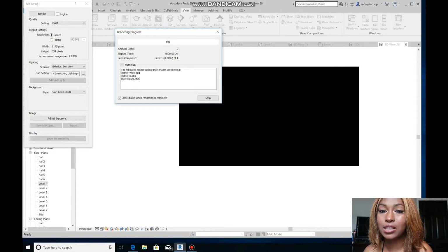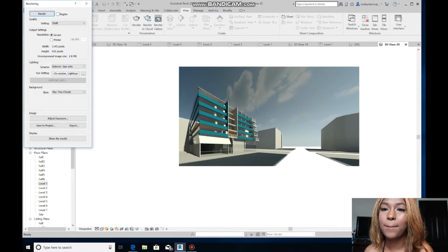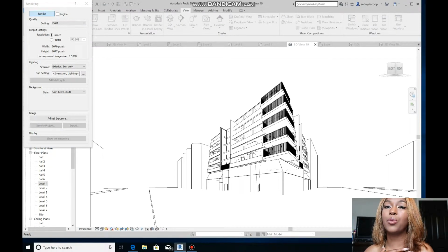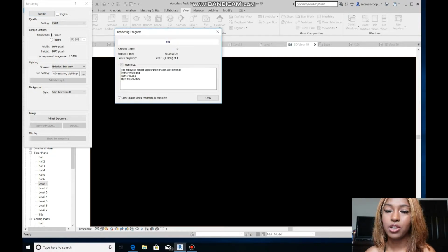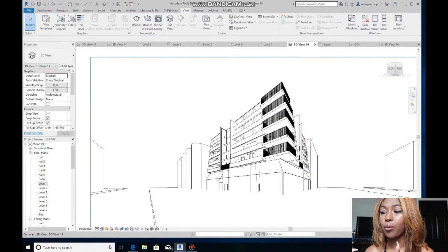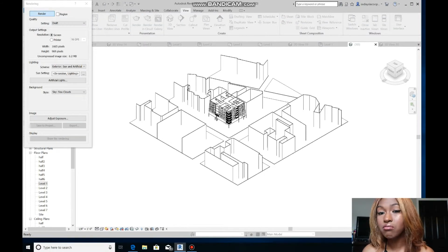One thing to take into consideration is I made all of the walls, basically all of the buildings, the same height as my building. This is not what you want to do for your real life project. You want to go and actually find the lateral dimensions of the buildings so that the shadows that are casted are realistic, the spatial integrity is kept, and that it's just overall more believable.